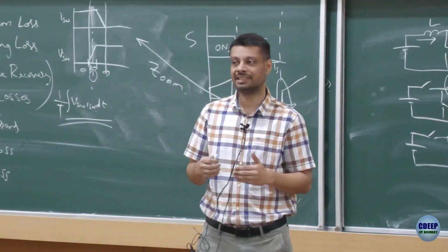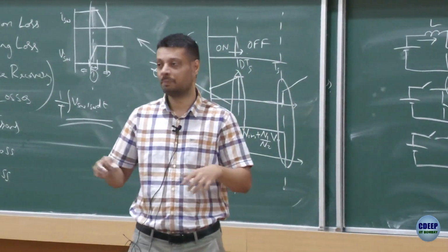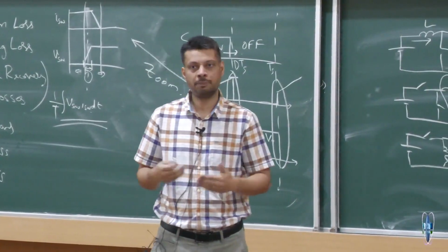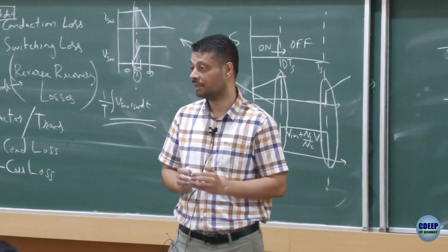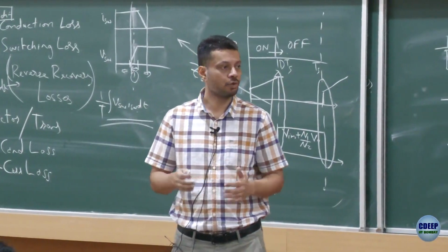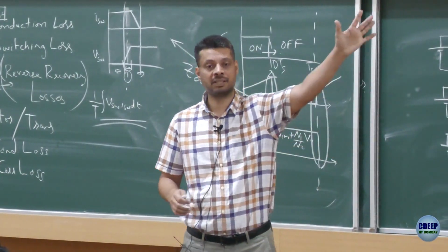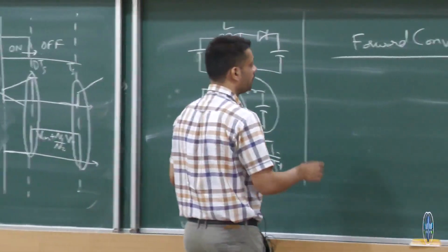So that is the reason it's not like A is always better than B, it depends on your application, on your situation. How it usually spans out is that for lower power, flyback usually works out very well. As you increase the power, slowly you shift from flyback to forward, and then from forward to a few other circuit topologies, whichever is more economical to operate.